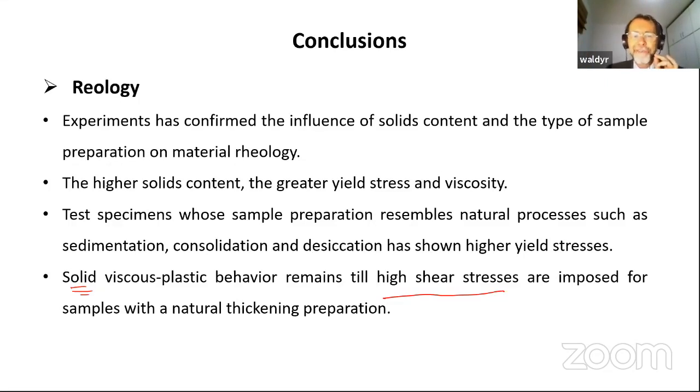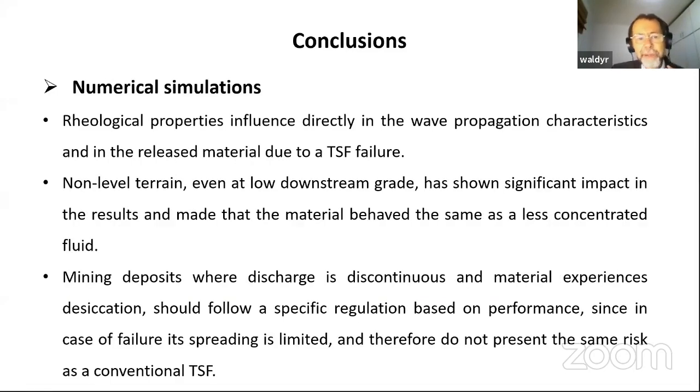So it's a different word, but one is the continuation of the other, okay? In the numerical simulations, rheological properties influence directly the wave propagation characteristics and the release of material due to TSF failure. So it's very important to do this kind of investigation properly, okay?